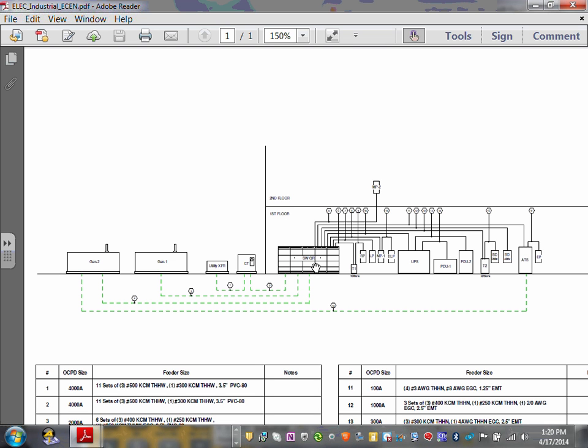That's the whole idea here. That's as high as, for the most part, as you can get with this equipment. So two generators back up the whole building at the 4,000 amp level and distribute the power. We have a mechanical panel too for the air handling unit. We have a two-story building, so we decided to put a mechanical panel because of a big chunk of load on the second floor, and we need to feed them.